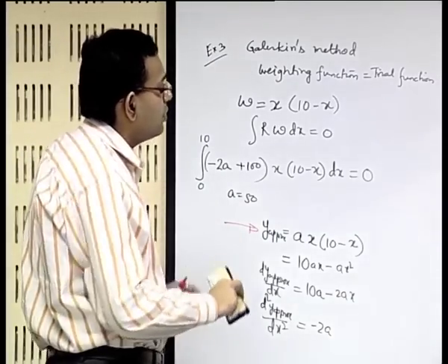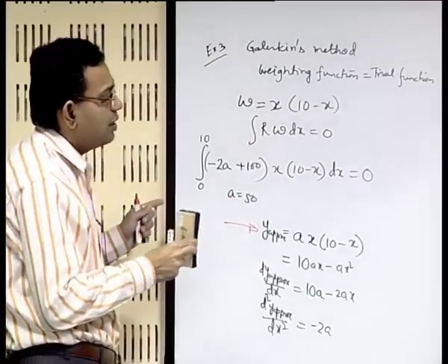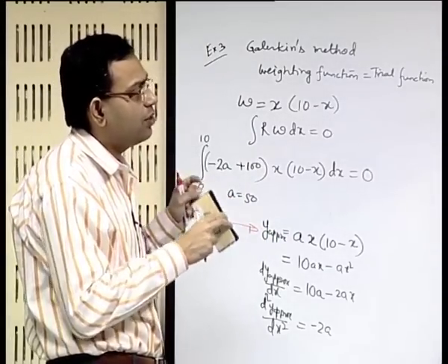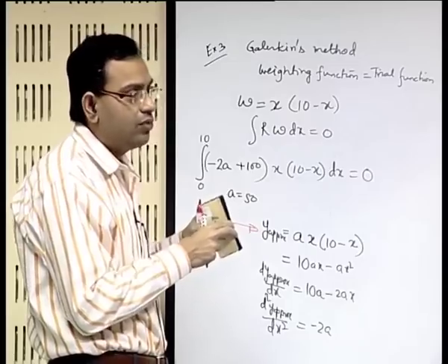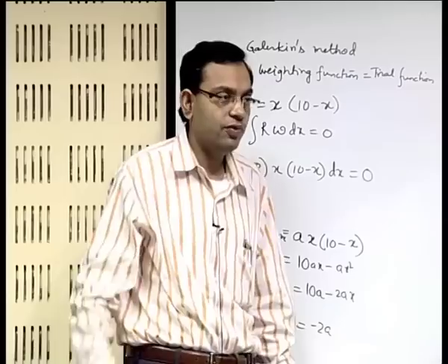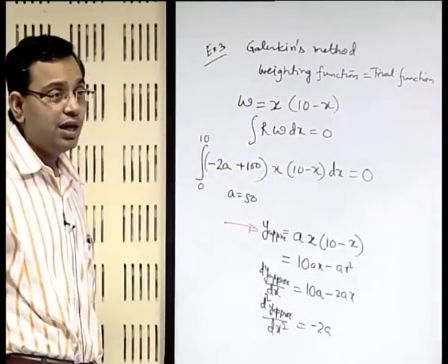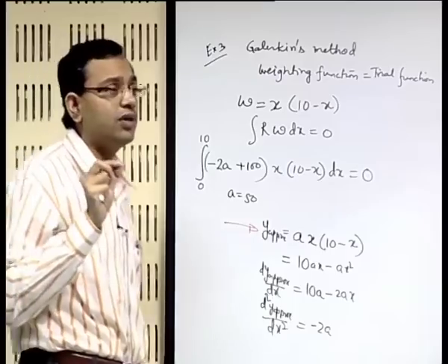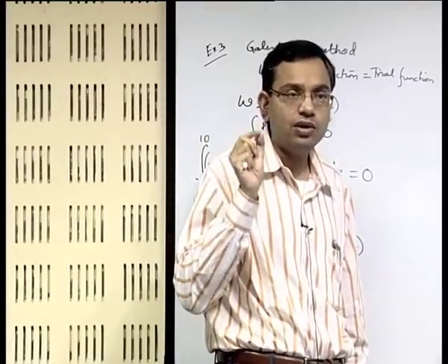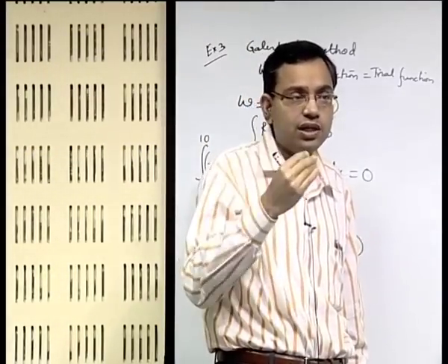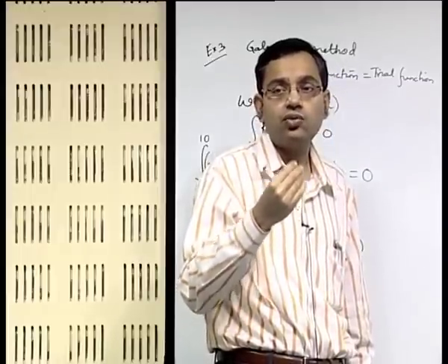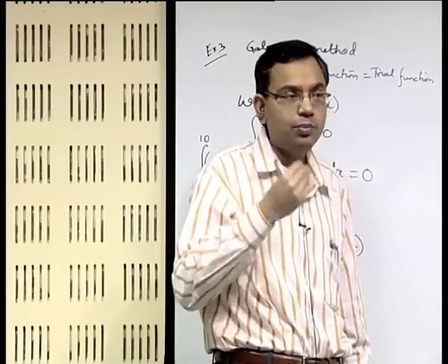Now we have seen 3 examples, and in all these 3 examples we have come through the route of the weighted residual technique, which has some resemblance with the V form or the variational formulation. Now remember that we had different forms of the governing equation. We had the original form as the differential form or the D form, we could reduce it to a V form, and subsequently we could also reduce it to an M form or the minimization form.